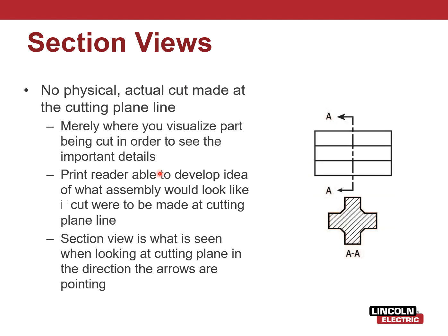So looking at this, if we saw this on a drawing, it's kind of difficult to tell what exactly this is, right? This could be like a top view of a T-joint. So we want more detail on what this is, what the shape or profile of this is. So you would do a cutting plane line, and do a section view.